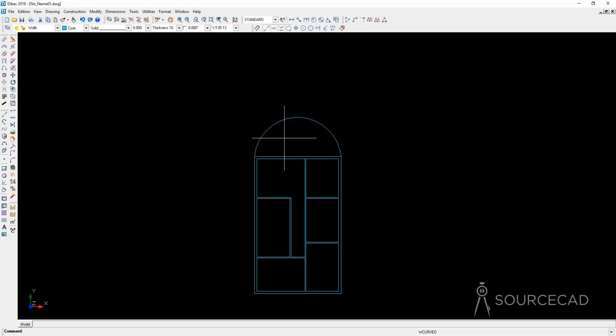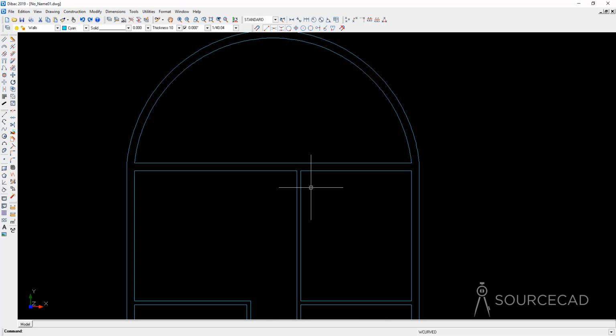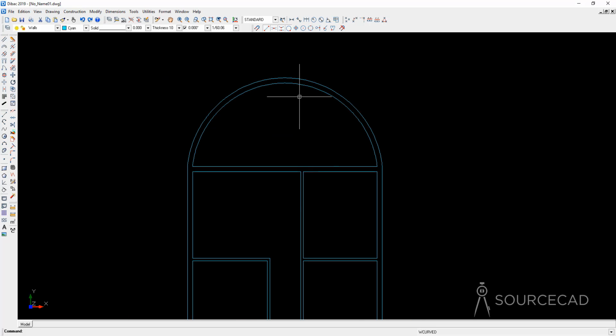Now we need to click inside because this is the way the wall is made. So I'm going to click here and now the walls are added. Also now here again, I will just add one more wall. So I'll go to this thickness of 10 and I'll go to the parallel wall tool. And from this point to this point, we need a wall, and that's added.